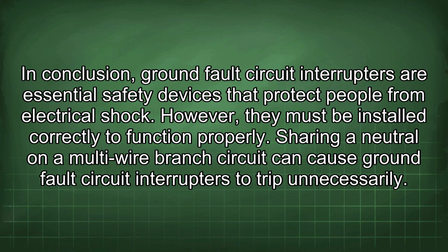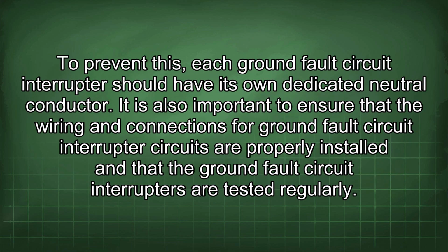In conclusion, ground fault circuit interrupters are essential safety devices that protect people from electrical shock. However, they must be installed correctly to function properly. Sharing a neutral on a multi-wire branch circuit can cause ground fault circuit interrupters to trip unnecessarily. To prevent this, each ground fault circuit interrupter should have its own dedicated neutral conductor.